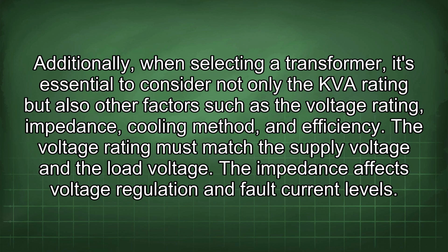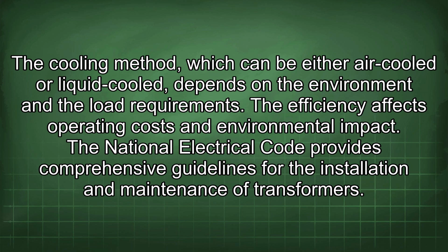Additionally, when selecting a transformer, it's essential to consider not only the kVA rating but also other factors such as the voltage rating, impedance, cooling method, and efficiency. The voltage rating must match the supply voltage and the load voltage. The impedance affects voltage regulation and fault current levels. The cooling method, which can be either air-cooled or liquid-cooled, depends on the environment and the load requirements. The efficiency affects operating costs and environmental impact.